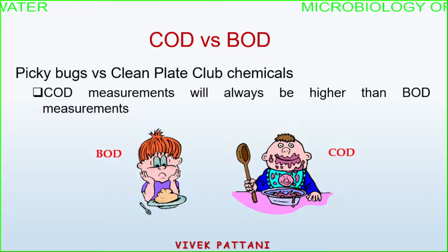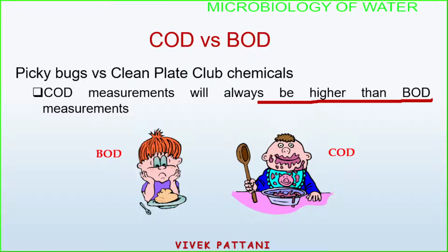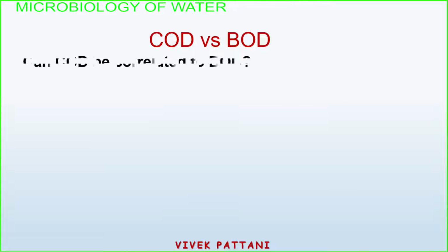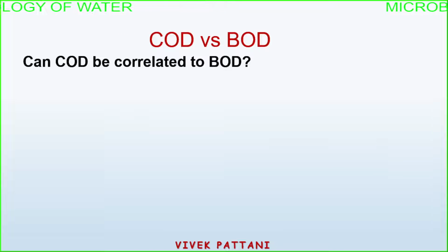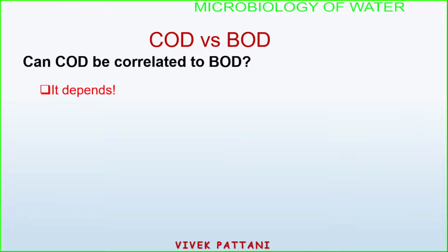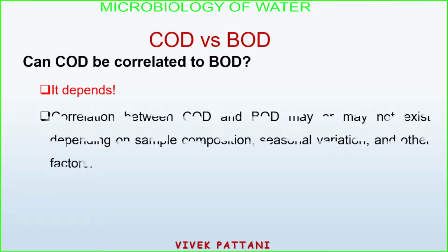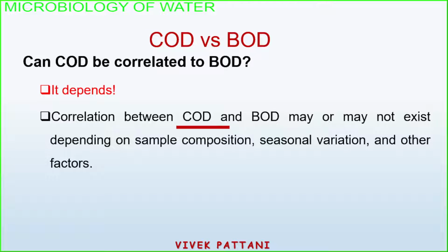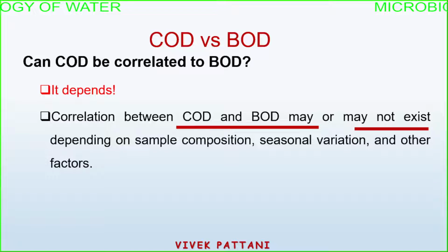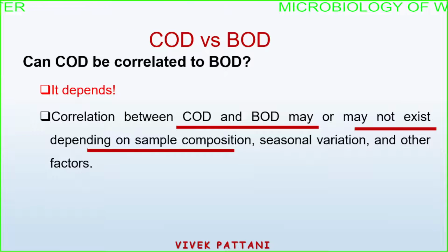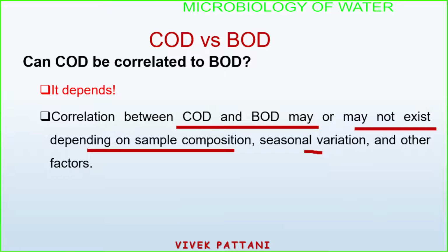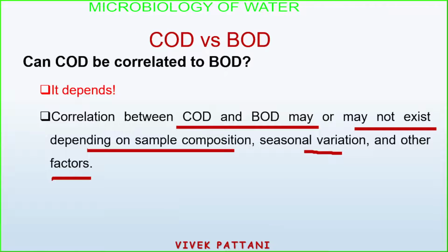Now, COD measurements will always be higher than the BOD measurements. Okay, always higher. Can COD be correlated to BOD? So it depends. Correlation between COD and BOD may or may not exist depending on sample composition. It also varies with seasonal variation and various other factors.